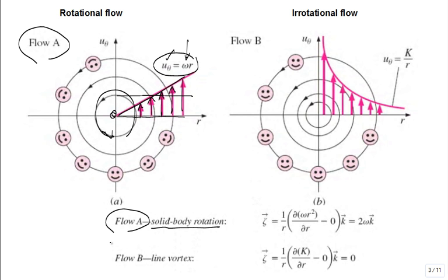And then you would just say, okay, well, tell me what the vorticity is, and you calculate it, and you find that it's 2 times the rate of rotation. It's 2 times the rate of rotation, or omega is equal to 1/2 the vorticity. Okay? Well, this would be a rotational flow field.